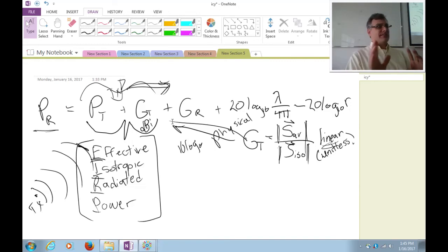Same thing with dBs, dBis, dBms, that's like the degrees. None of the physics actually works out in that scale, but it's a very convenient way to report the number. Whereas radians are like the natural linear units in the free space equation. That's how you do all your calculations. It's only for reporting convenience when you're trying to grasp how much this power is, how big of an effect it will actually have.